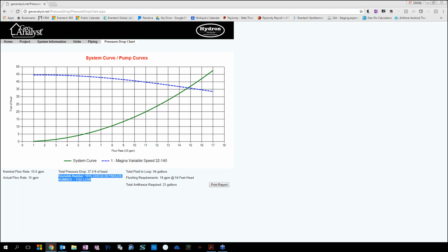If you were to freeze time, dig out your ground loop, slice it up like salami, a low Reynolds number would look kind of like a tie-dye t-shirt. The middle of the fluid is not getting any heat transfer. The only part of that fluid slug that is getting any heat from the earth is the perimeter. So just keep that in mind when you're looking at this.